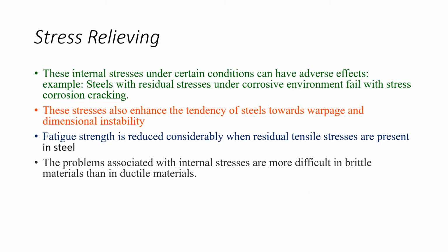Stress relieving. These internal stresses which were developed in the structures, under certain conditions, can have adverse effects. For example, steel with residual stresses under a corrosive environment fails with stress corrosion cracking.